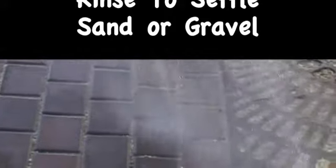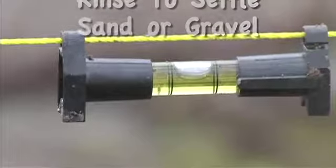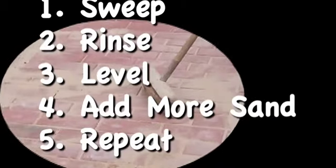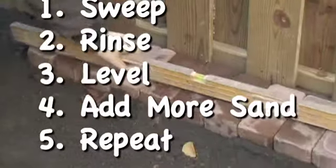Rinse the paver structure to settle the sand. Check once again to ensure that the pavers are level and add sand to the spaces as needed. Repeat these steps until the structure is stable and ready for use.